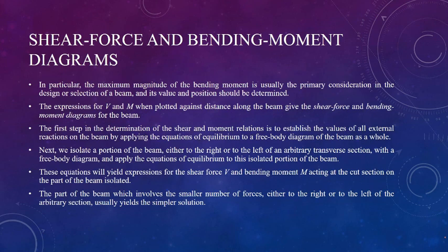Finally, once you have developed, I will repeat it again, once you have developed a free body diagram, established all reaction forces, external forces applied or in response to the joints such as pin joints, roller joints or concrete sections, they all will generate a reaction forces. Once you have established a free body diagram, you're going to start isolating it. Then you're going to start isolating your each point. You're going to either start from the right hand side of the beam or the left hand side of the beam. From there you're going to move section by section.